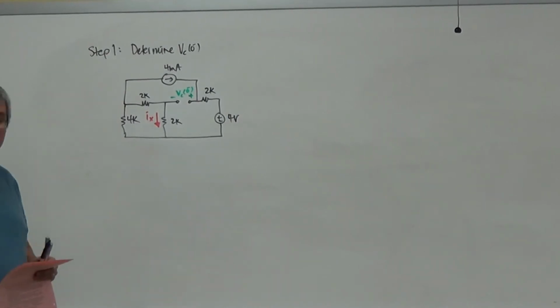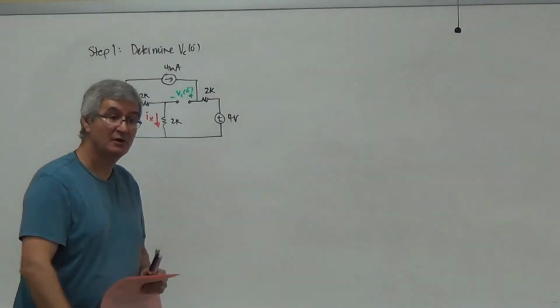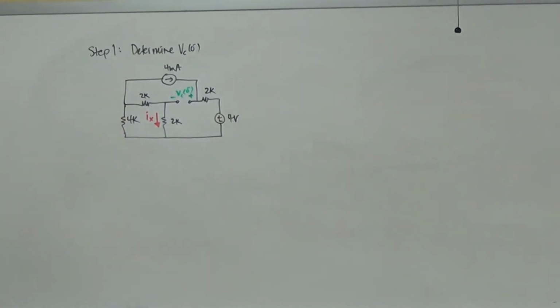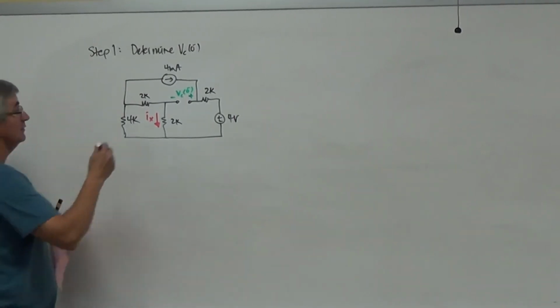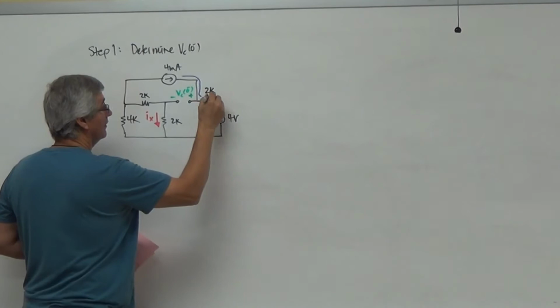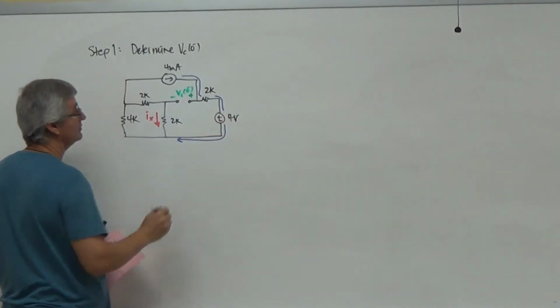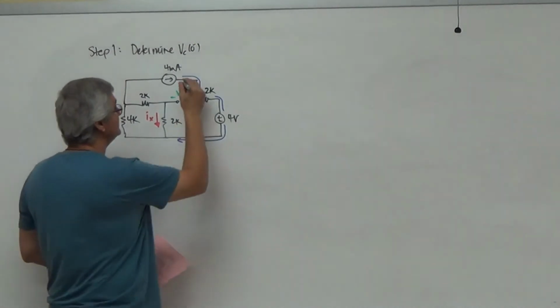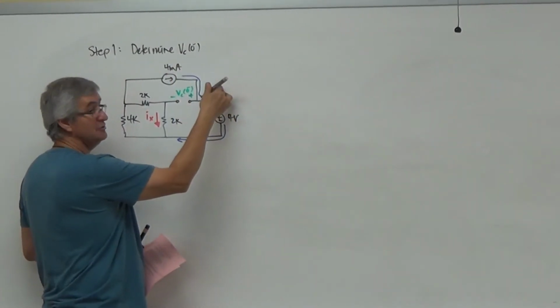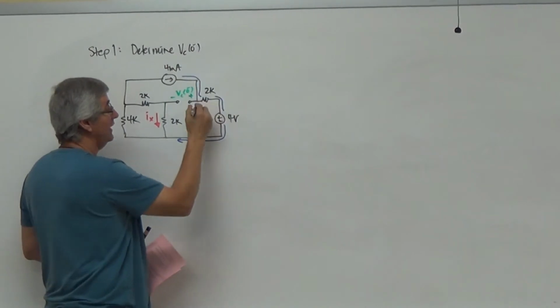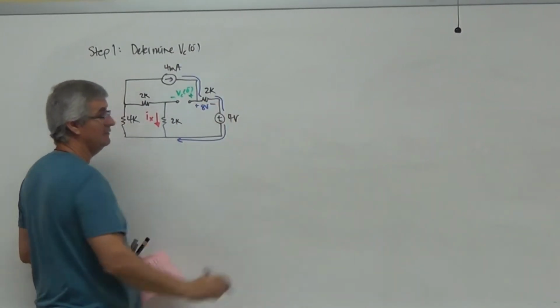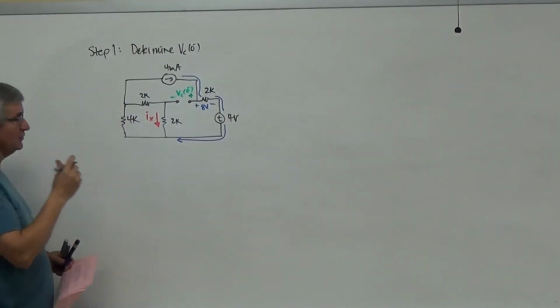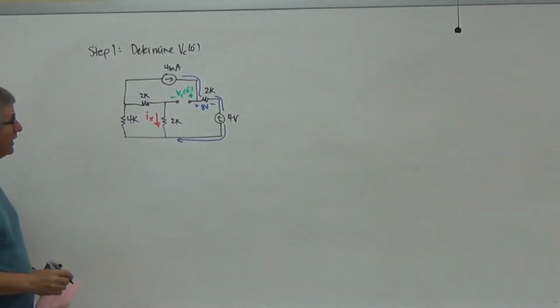Simple circuits, mesh, node, Thevenin. Hell yeah. Just look at that circuit. Follow the current. Look at the current. I know the current right away. So I know that this guy is 4, and that's a 2K. So 4 milli 2K, that gives me what? 8 volts. Okay? So I got that voltage, I got that voltage, but wait a minute.